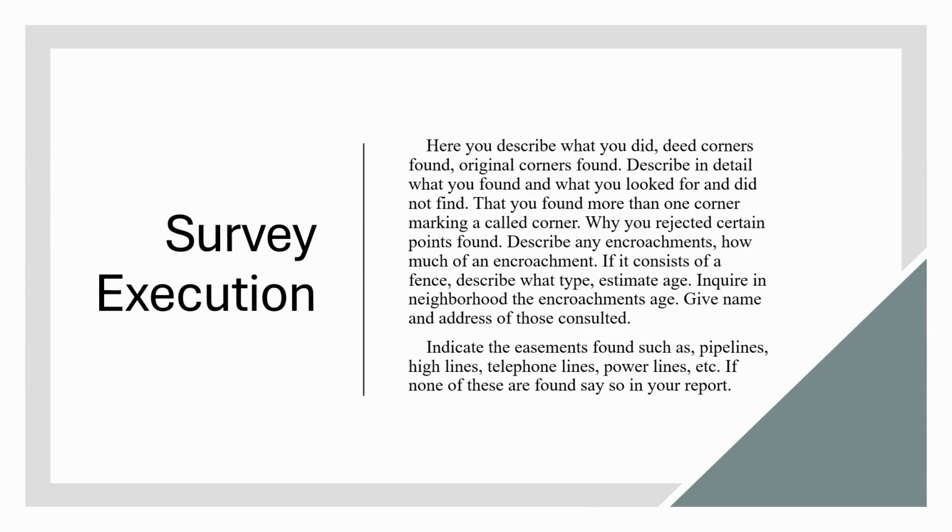What was your thinking as you were going through and doing this survey? Found encroachments, where were they? How large were they? Why do you think they're an encroachment? Can you identify potential past agreements or easements that would have allowed an encroachment? All of this information is going to be relevant.